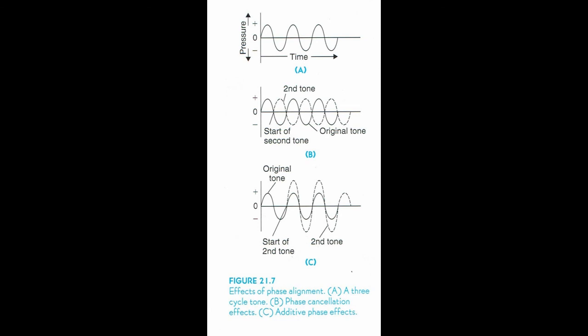It's important to know a signal's phase, whether that signal is an electronic, analog of a sound wave, or an actual sound wave itself. The reason is because the intensity of the sound will be affected if the signals are out of phase. If one starts at the exact same time as shown here, what actually happens is you get what is known as phase cancellation.